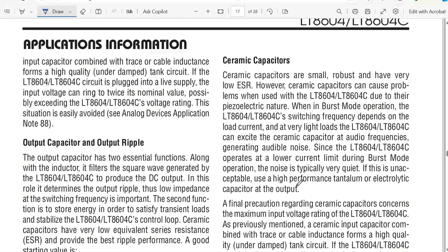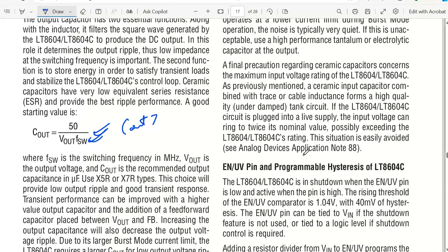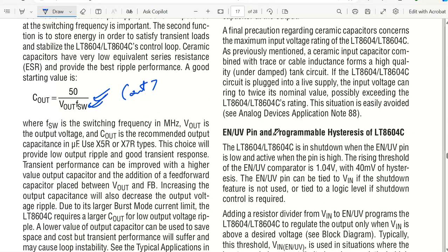Now coming back to the next part, which is going to be the capacitor. If you want a very easy design, you use at the input an electrolytic capacitor in addition to a ceramic capacitor. Similarly, the output capacitor also has this configuration, which is more than enough for your design. Coming back to the ceramic capacitor side, because you have a space constraint, you can utilize ceramic capacitors of somewhat lower values, but 100 or 120 microfarad should be enough for your input capacitors.